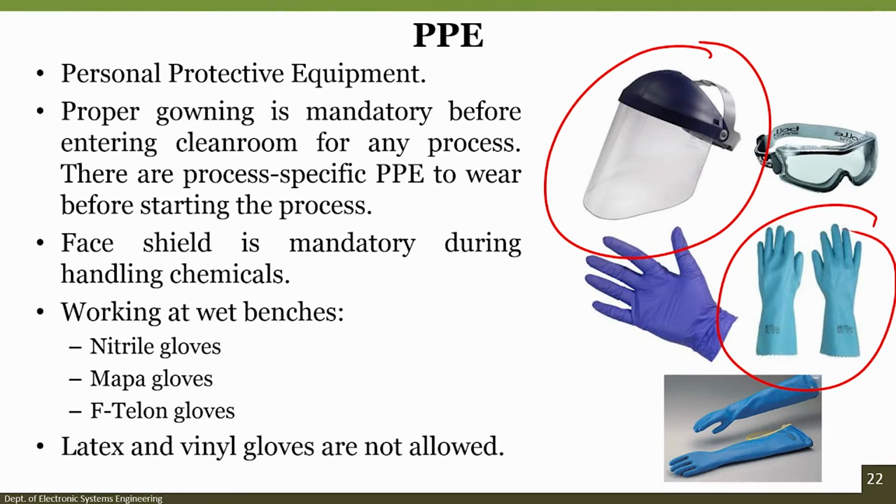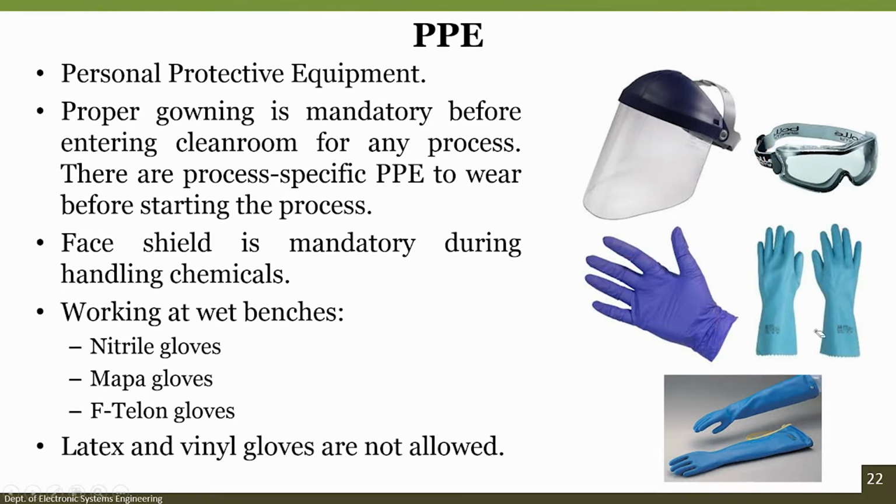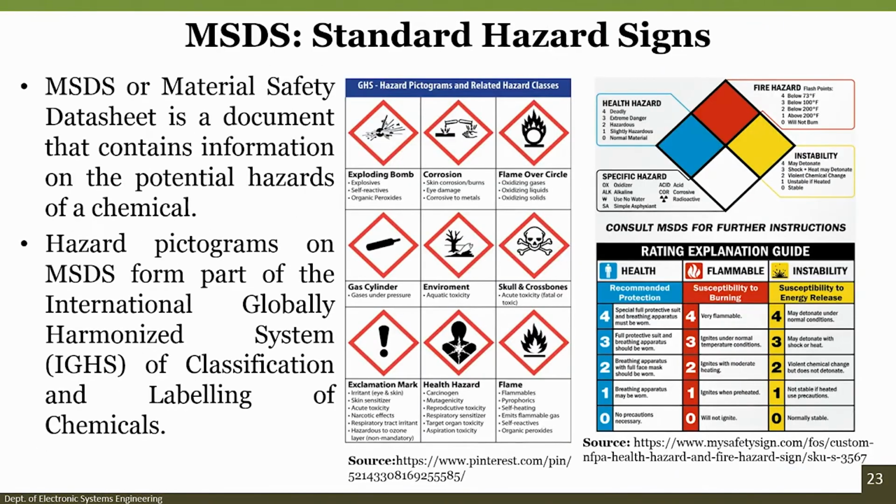Another thing we need to understand is that when working at wet benches, you have 3 different kinds of gloves. One is nitrile gloves, another is MAPA gloves, and the last one is Teflon gloves, while latex and vinyl gloves are not allowed inside the clean room.